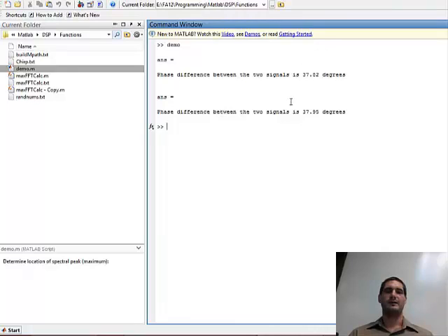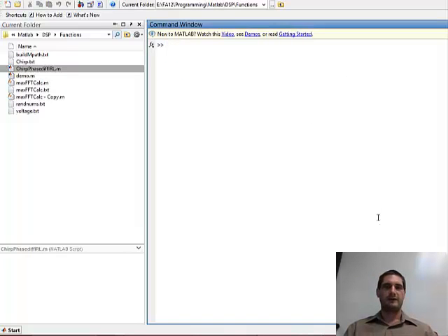This frequency was applied to two signals, one of which was phase shifted from the other by 37.95 degrees. Now, this top one is the FFT signal. Notice how the phase is not exactly the same as the 37.95 degrees, whereas the chirp Z transform is spot on. Once we had some of the hardware built, we moved from simulating the chirp Z transform to actually implementing it on data that was sampled using our hardware.